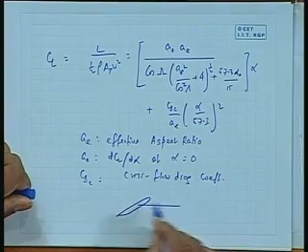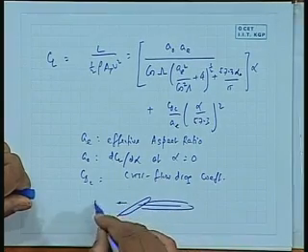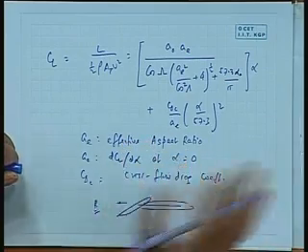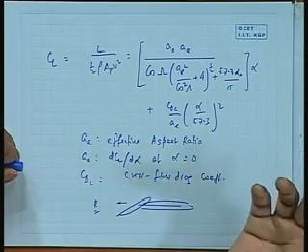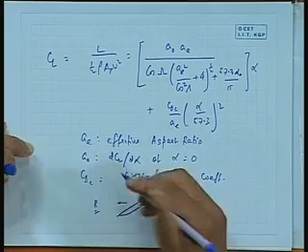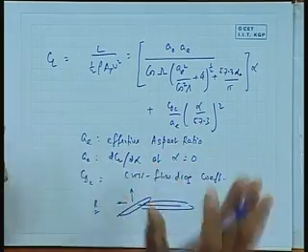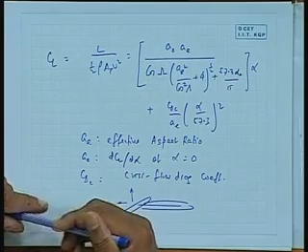But the essential features that I wanted to mention are these: you need to find out the force coming on the rudder, because the more the force, the better. The force comes from lift and drag. There is a drag also coming. When you turn the rudder behind the ship, it increases my resistance. That is the reason why my ship slows down. You want it to slow down less, but you want to turn more. So you have this CL, CD phenomenon. This is why we have gone from a plate to an aerofoil section.